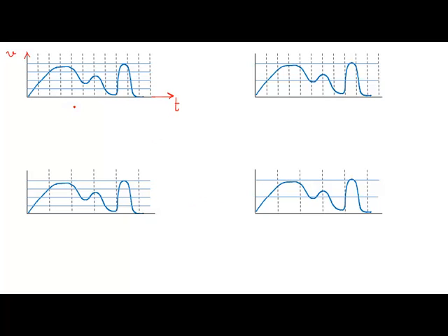So you use a conversion mechanism that basically says, take one sampling period and take the average value of the signal, and divide the voltage range into the number of segments that you have here. Then if I divide the real voltage value by these numbers and truncate it, that will be the value that I'm dealing with.